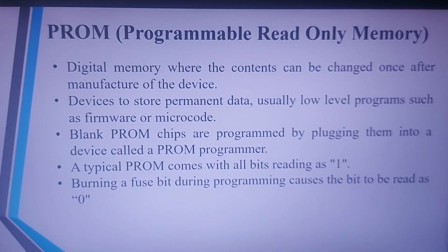If the configuration is not required to be modified, then whatever programming has to be done in those particular ICs will be done at once by the developer, and then they will be put into the machines. Especially in washing machines or microwaves, the programs usually will not change. So there will be a particular configuration which will not change, and those configurations will be put on OTPs or PROMs.